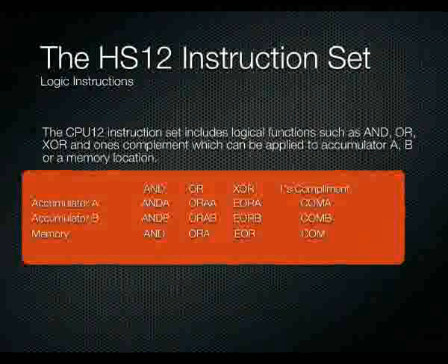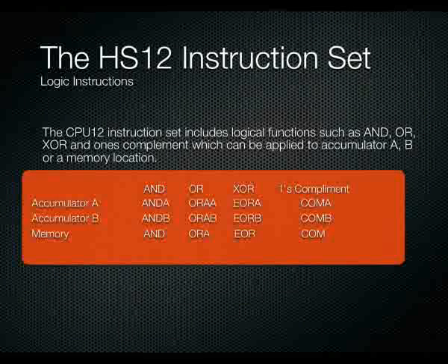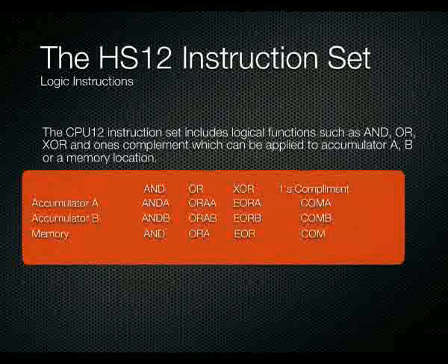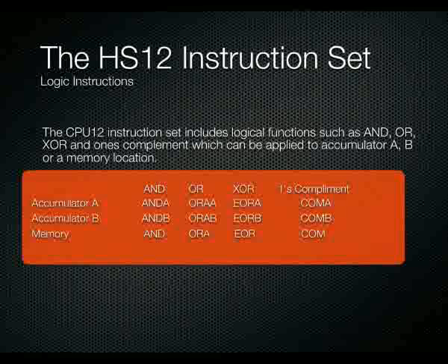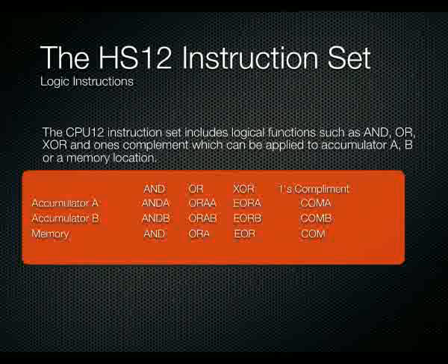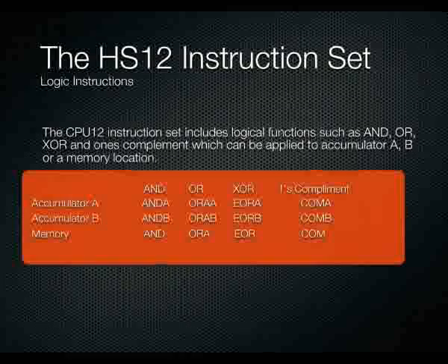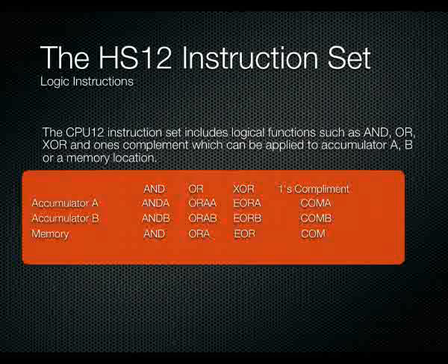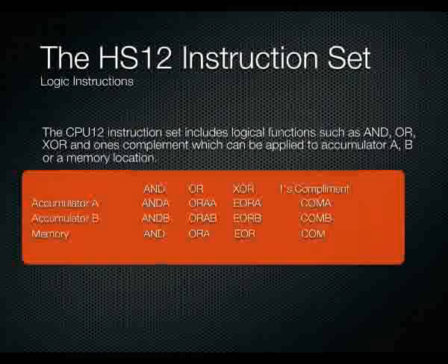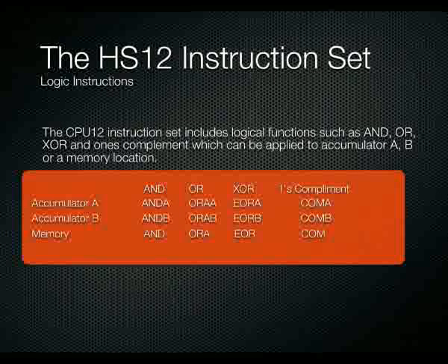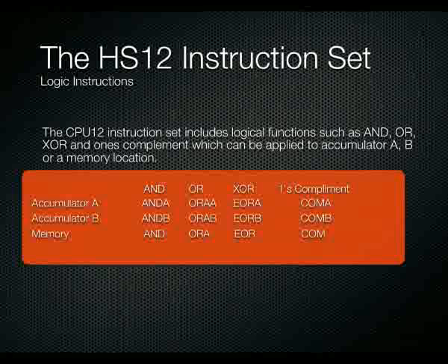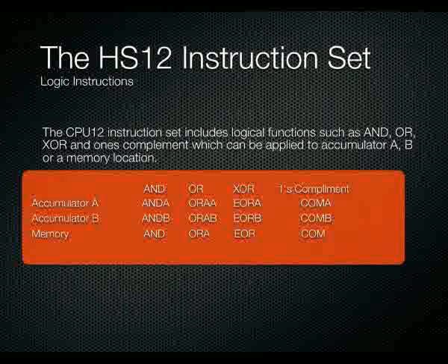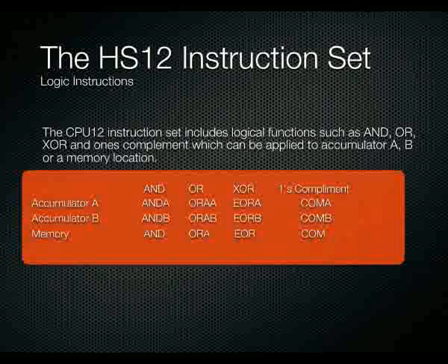So not only can our arithmetic logic unit do arithmetic instructions, but it can also do logical instructions. The logical instructions that we can do in this ALU are logical AND, logical OR, logical XOR, and we can do ones complement. When it comes to accumulator A, we can do an AND with ANDA, an OR with ORAA, an XOR with EORA, and a ones complement with COMA. The names of those mnemonics sort of give away what instruction we're doing.